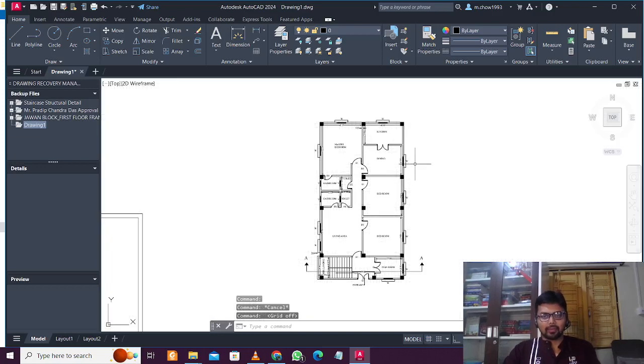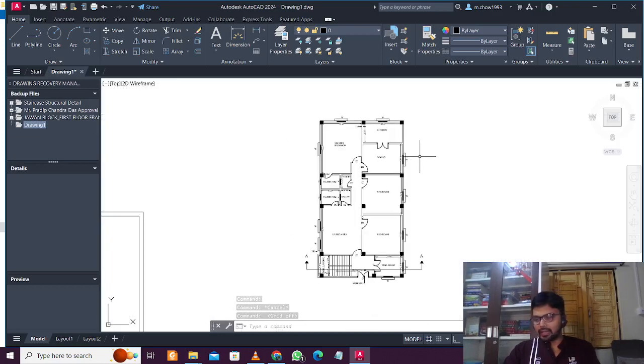So this will be a full course on how to design a building in STAAD and RCDC. We're going to go by the equivalent static method in this particular video, and the process of RCDC stays the same for the equivalent static method and also the response vector method. But I will also do the response vector method in another video just to show you.